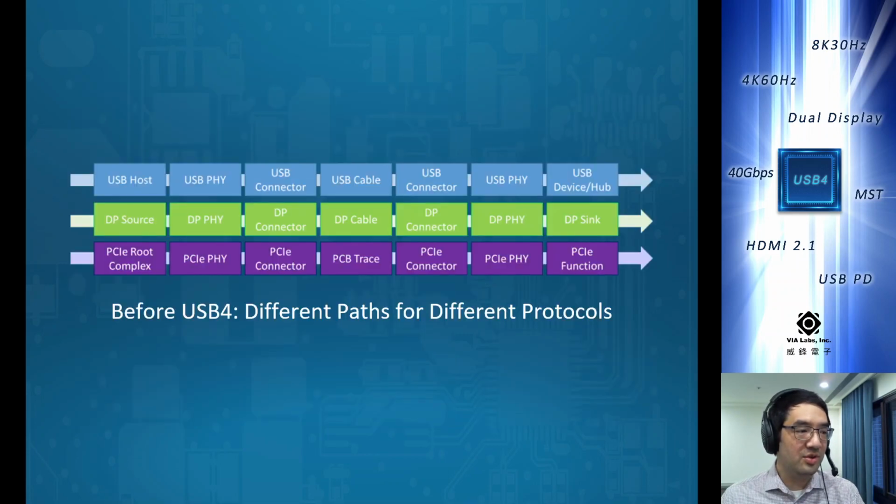On this page, we're just going to be looking at how USB 4 compares to previous times when we didn't have USB Type-C. In the past, when you had different protocols like USB or DisplayPort or PCI Express, you had a single function connector and cable, and they weren't interchangeable. For example, HDMI works great for video, but you're not going to be able to get meaningful amounts of power out of it. And with regards to PCIe, for most end users, it's really just a board-to-board interconnect between the CPU and storage to expansion cards or maybe graphics. And it's all within the same box.